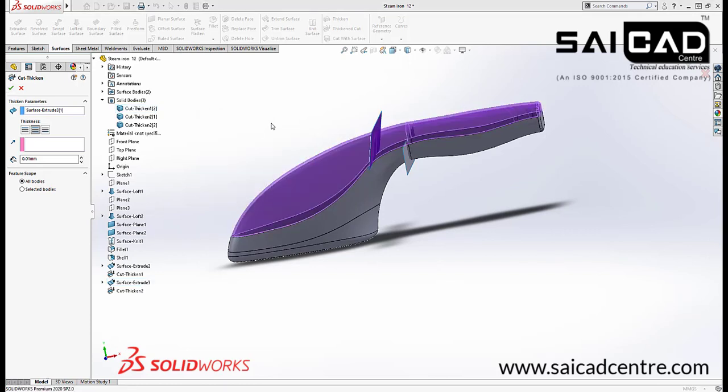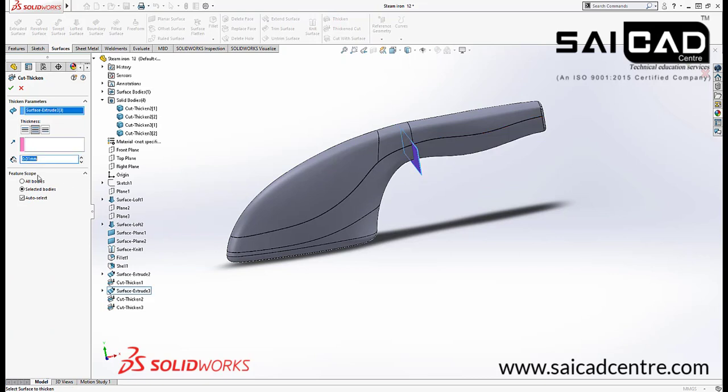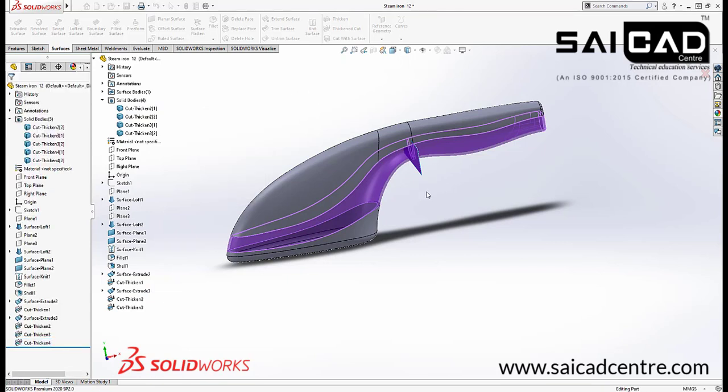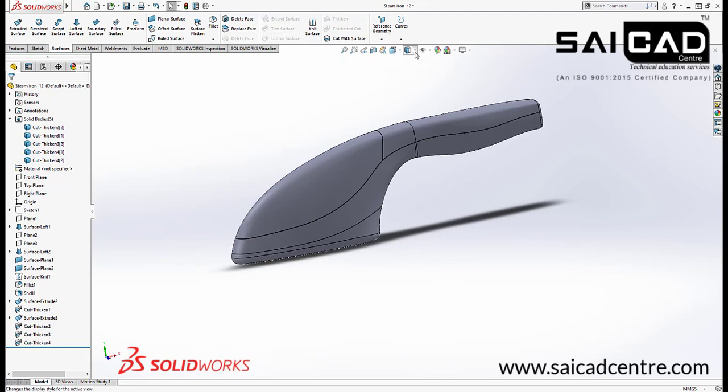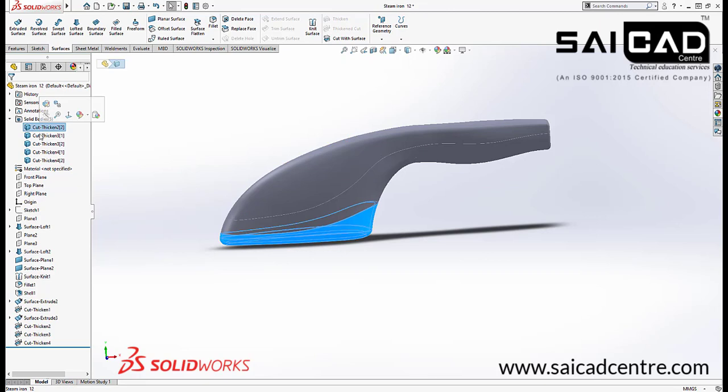I need all bodies. Okay, so this body will be separated. Now we need a thicken cut with the help of this one, and all bodies from here. Okay. So now if I just select all the bodies separately, you can see that we are having different bodies.